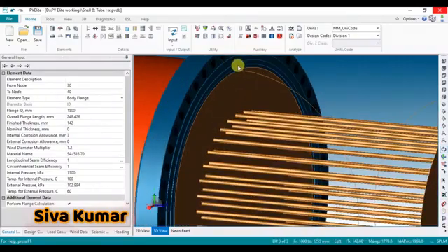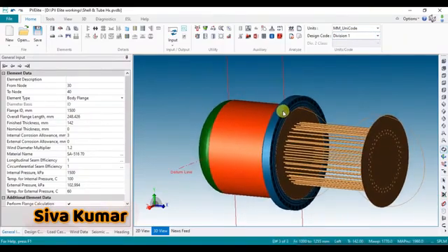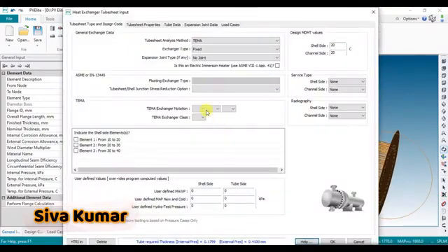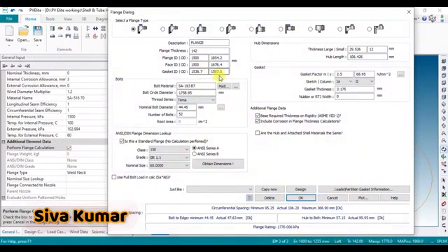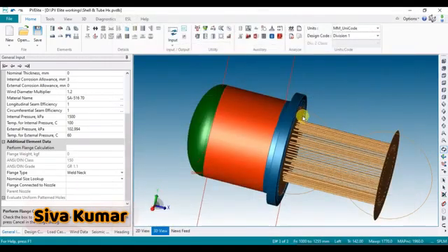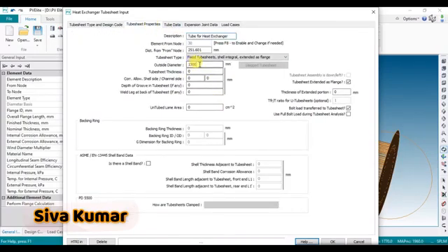So see, this is what our tube. So you can cross check this flange. So here I can click this flange. The flange OD it is 1675. So here you see 1855, and in this tube sheet, so the OD we can enter 1865.